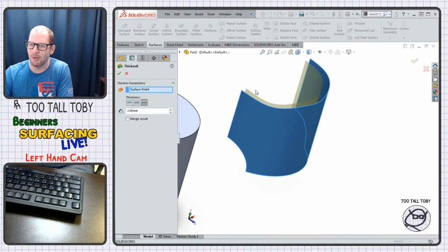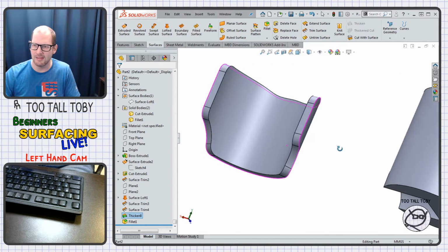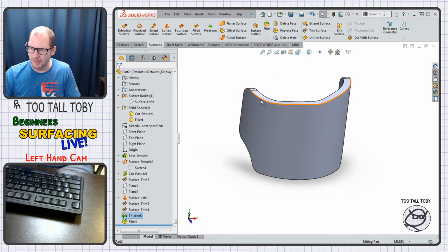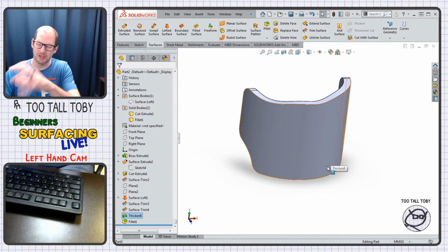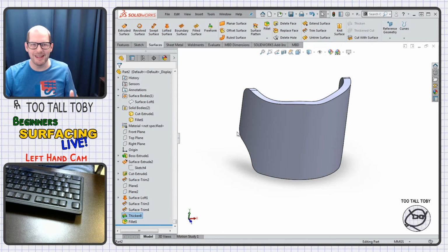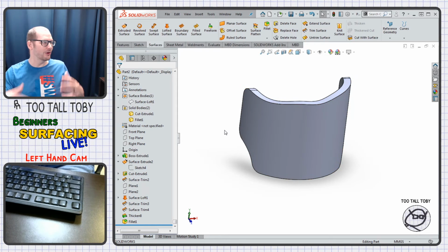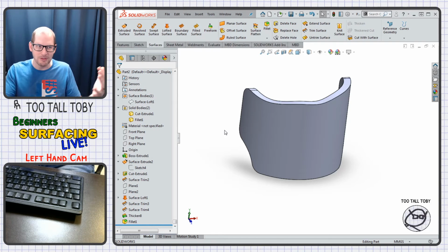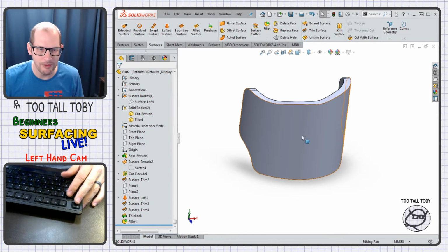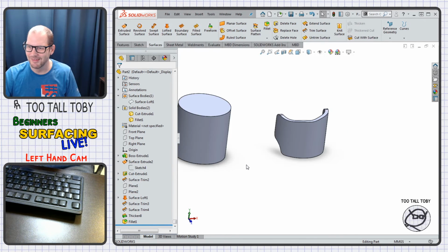Maybe the sidewall, instead of being cylindrical, is lofted, and then from the lofted geometry you're getting this wall thickness. You've got this lofted geometry, and then you're doing your trim to the lofted geometry. Whatever it is, you can see there are some really powerful tools you can learn just by learning how some of these trim commands work. Trim, thicken, surface extrude, surface loft, one face at a time. Yeah, turn it into the Iron Man mask, exactly.